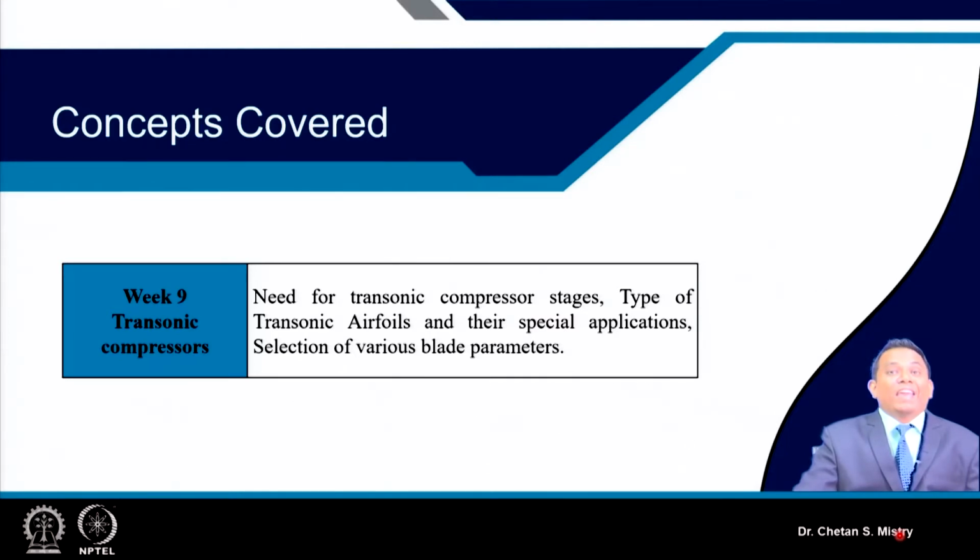We have discussed the S type of aerofoil, and later, after understanding the flow structure, we tried to get the camber line required for generation of these aerofoils. We also discussed the distribution of thickness over this camber line. We considered circular arc thickness distribution, and then a standard thickness distribution. Then, after having all this idea, we made our aerofoils, which we will use for our future design. This gives a brief idea of what we discussed in the last session.